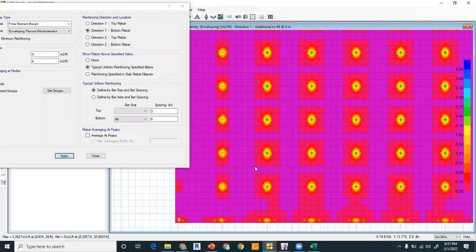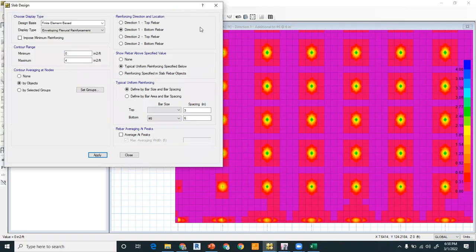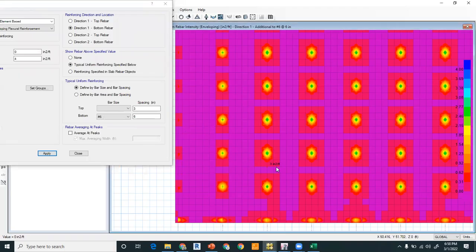At the corner, the coordinate in X is 43 and at the other end it is 56. So it is almost 13. You can go for 15 or you can go for 13 as well. Normally you go for 15 because the bar length is 40 feet, so there will be no wastage of the reinforcement. So in X direction, the length of the bar for the second layer is 15.